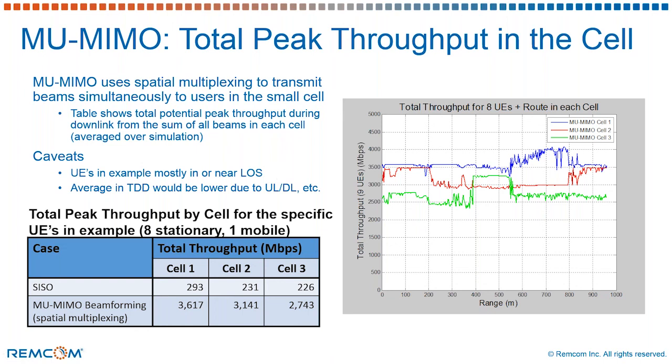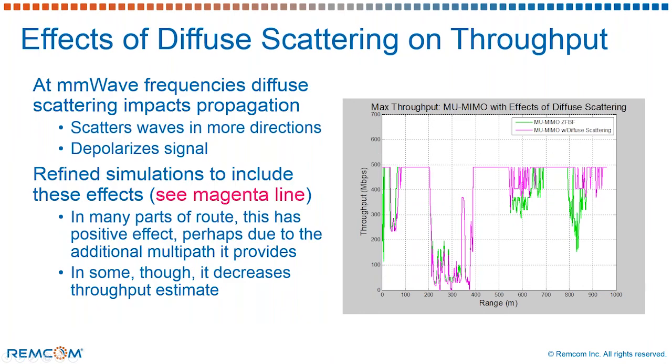Next, we looked at coordinated multipoint, looking specifically at joint transmission to see if this might be able to assist, particularly near the cell edges where we still are suffering the dropouts along our mobile route. So in this case, we looked at the cell edges, and in those locations we modified the beamforming from the zero forcing algorithms to attempt to have two base stations transmitting along the cell edges between them at any given time at the same time to a device. This essentially doubled the number of transmitting antennas for that portion of the route, allowing for 256 transmitting antennas to beamform to that device.